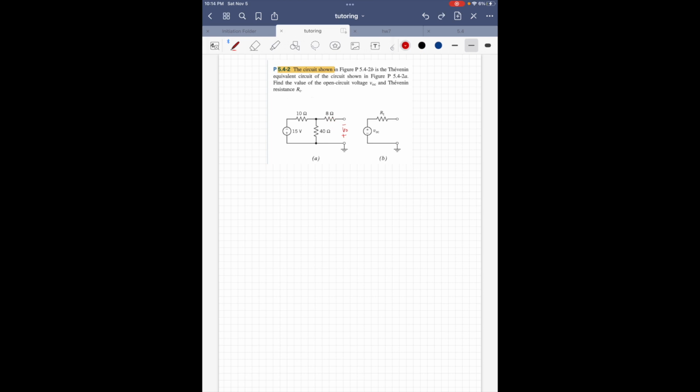So this resistor, in this case, we can actually ignore, because it's not participating in this voltage drop. There's no current going through it. So now that we're going to pretend that we don't have this resistor for now, finding the Thevenin voltage is hopefully clearer to you now, because we have a source voltage and then we have two resistors in series.